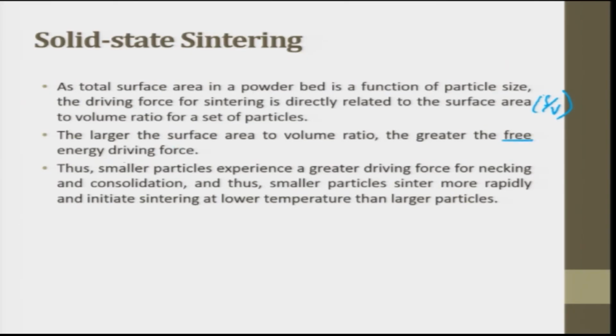So, you will have a greater energy drive to push the particle. Thus, a small particle experiences a greater driving force for necking and consolidation. Thus, smaller particles sinter more rapidly and initiate sintering at a lower temperature than the larger particle. Very important point: if you can go smaller and smaller in the size of the powder, then you will have more driving force, in the sense that you will get better consolidation.